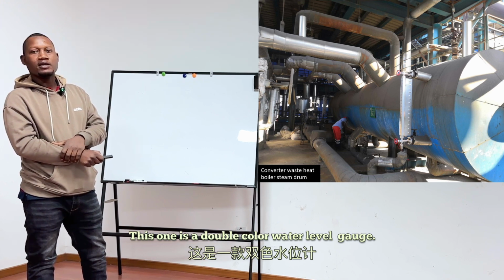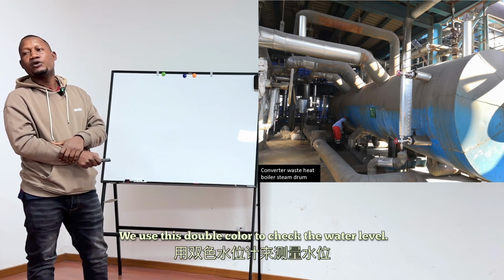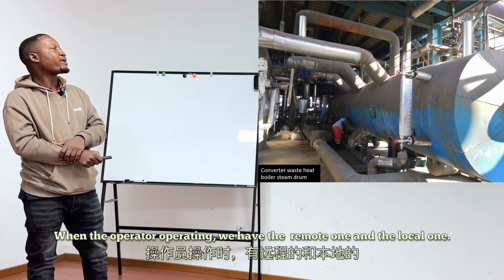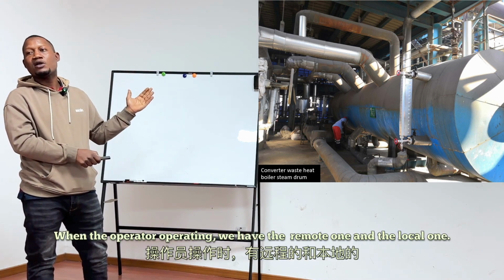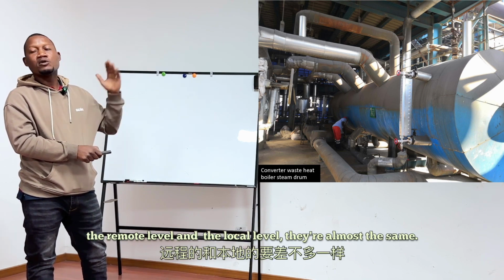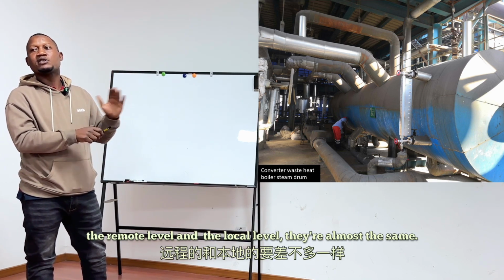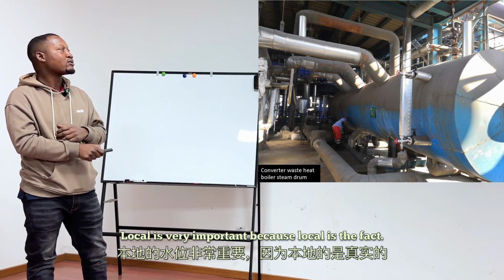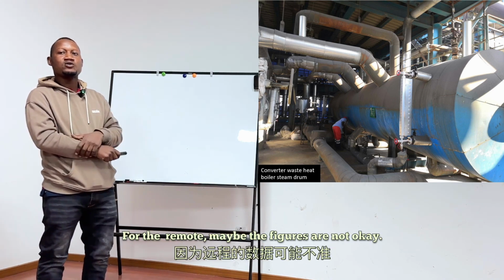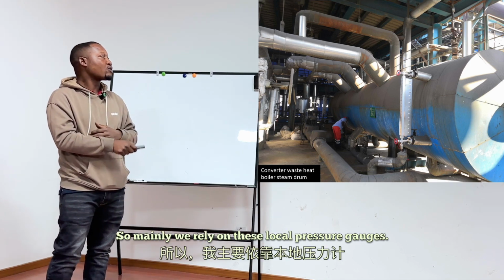This one is a double color water level gauge. We use this double color to check the water level when the operator is operating. We have the remote one and the local one. So it's very important to make sure that the remote level and the local level are almost the same. Local is very important because local is the fact. For the remote, maybe the figures are not okay. So many will rely on these local level gauges.